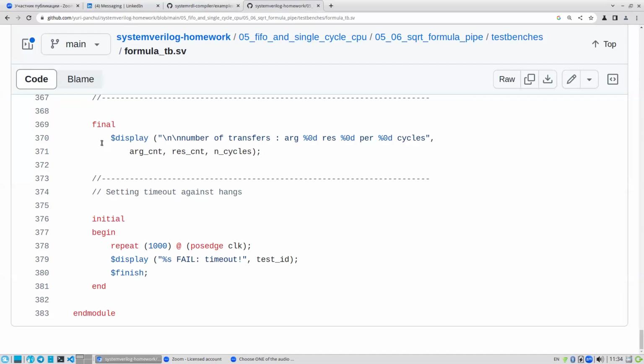There is one support for UVM, which is the accelerated UVM, that is running the actual RTL in our FPGA, and running a simulation in our system that is taking the transactions from the real RTL and comparing with our system in UVM. Ah, okay. So you're putting the RTL on a prototyping FPGA board, and you put some logic and code so that your UVM test bench talks to this FPGA board, right? Yeah.